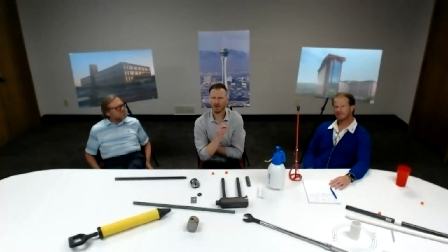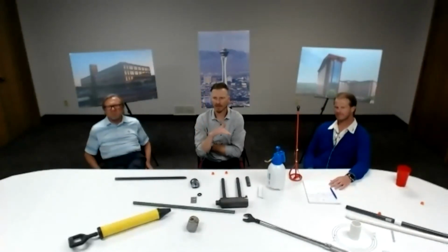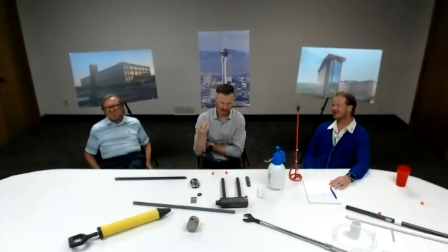So maybe one or two more questions here, because this is good. This comes up: can you cut the grout tubes off at the slab elevation prior to the pour? Yes, so the finishing guys would love this, and you can do that. We haven't toyed with that idea, but you just have to make sure you get your elevations done properly.